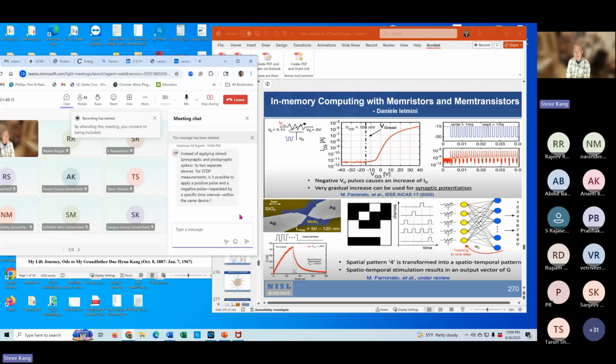You have to have a neuronal-like signal, right? So it has to be in that range to have proper operation. A neuronal signal in a real biological system is minus 70 millivolt to positive 30 millivolt. But depending on the memristive characteristics, the set voltage and that range, you can operate the voltage level according to that device. So you have to know the device characteristics and then set the amplitude of the signals.